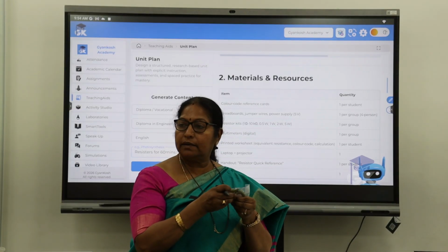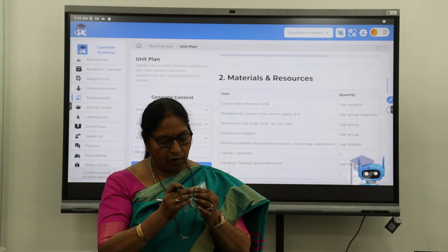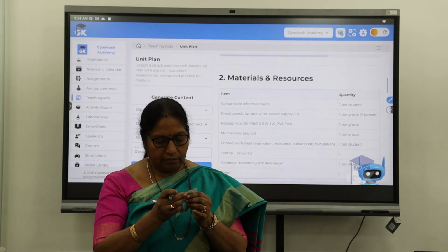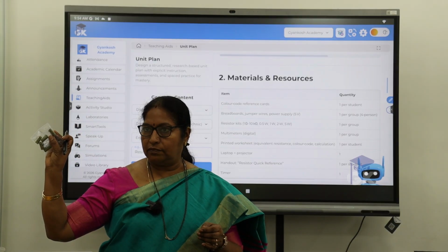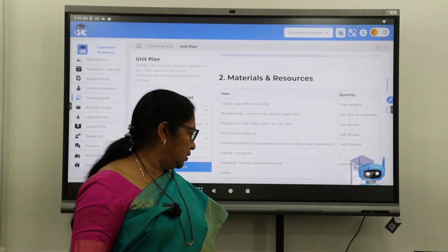And how do you check it? I'll tell you how the wattage is checked. Normally in wire wound resistors, they write it on the resistor itself. You can check it. Tell me what is the wattage written on that?